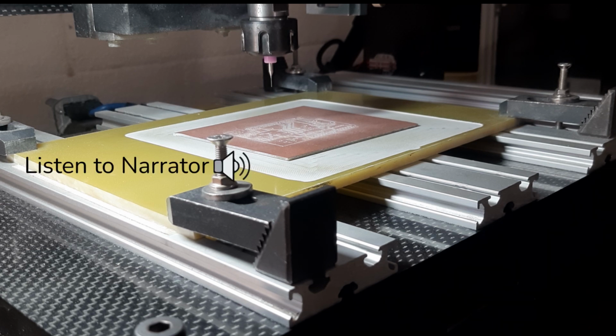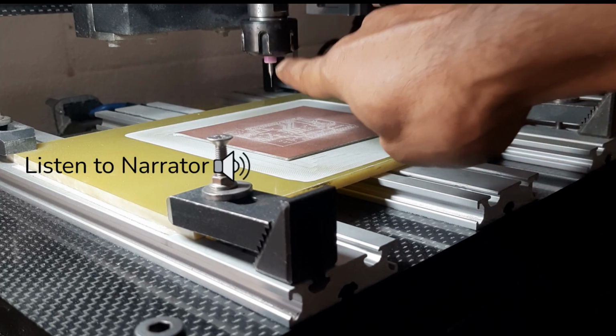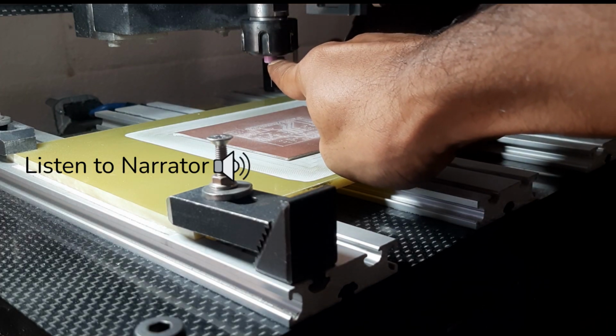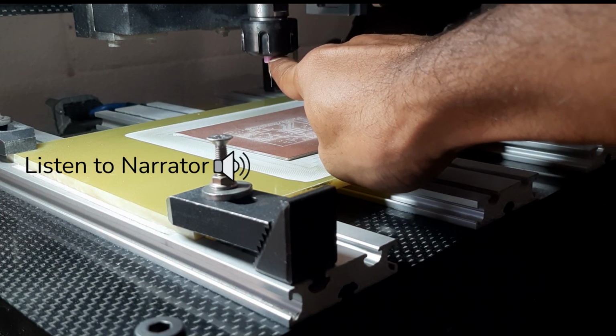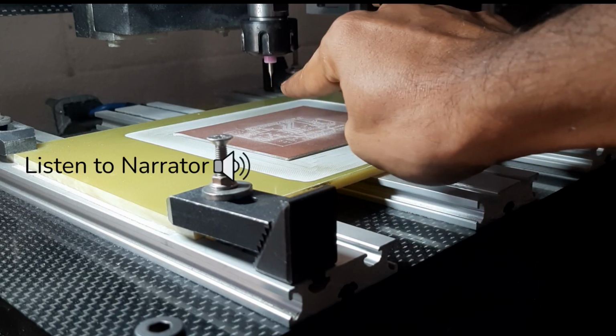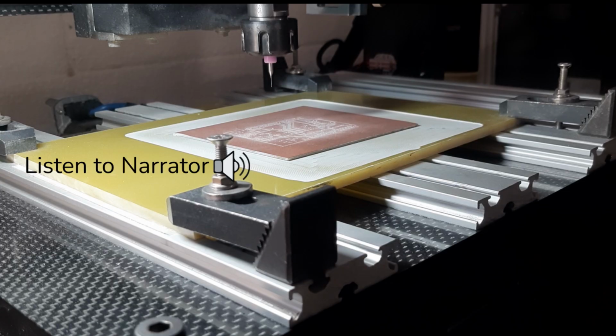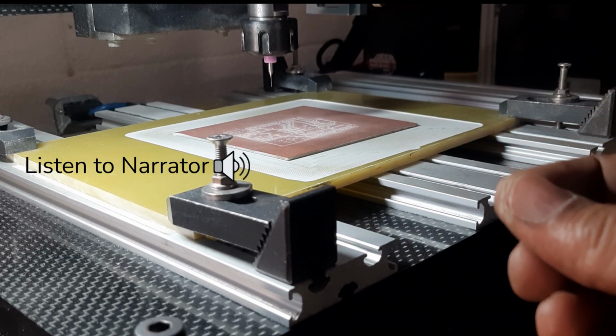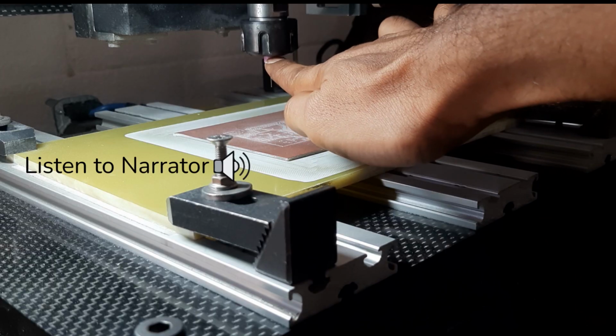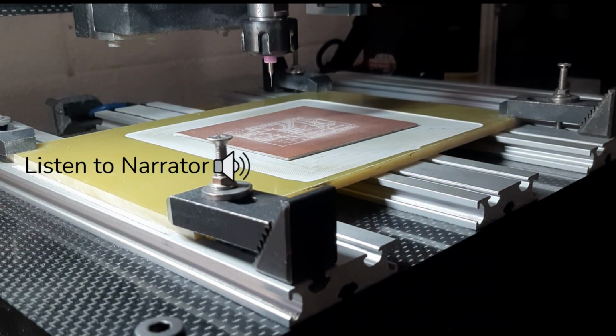Starting of the drilling process, start with the smallest drill bit, in this case 0.3. The drill bit is loaded with the collar all the way up to the collet. This way, when we change the drill bit to the next one, we have to put the drill bit with the collar again all the way to the collet, so no need to find Z0 a second time.